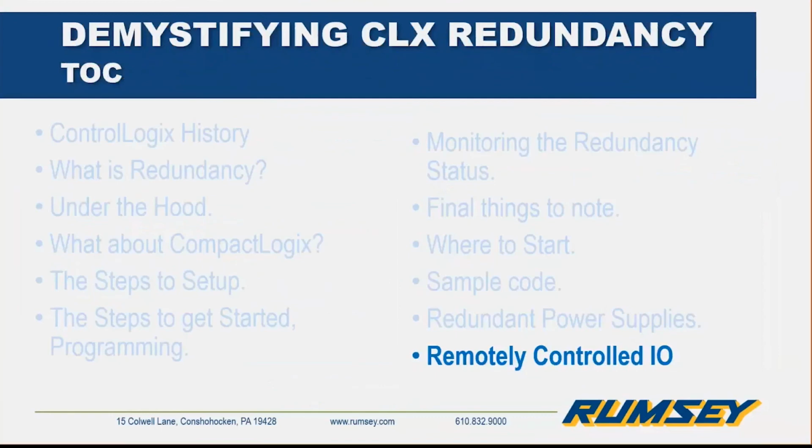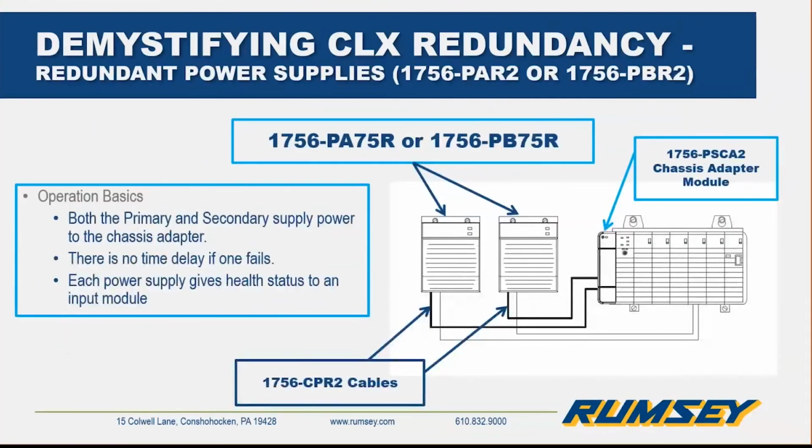And those power supplies, they can be wired remotely. They don't have to attach directly to the rack in that application. They do have a custom cable that goes between each power supply and that chassis adapter module. Yes, because there's a whole health thing going on. There's a particular current level that's transmitted. In other words, they have to be fairly close. I want to say they're 3 meters or less.